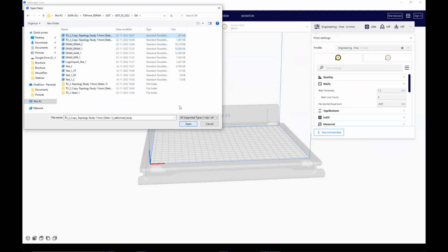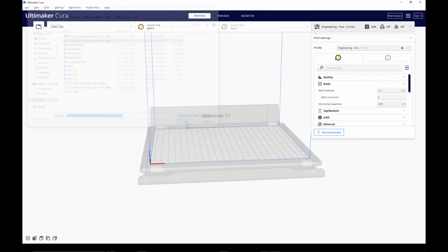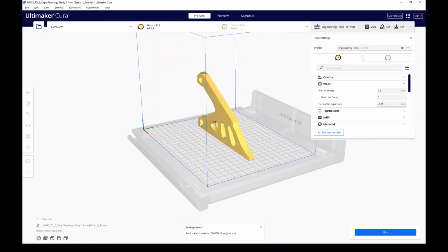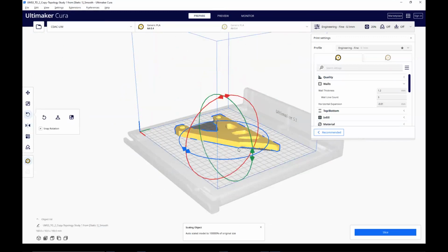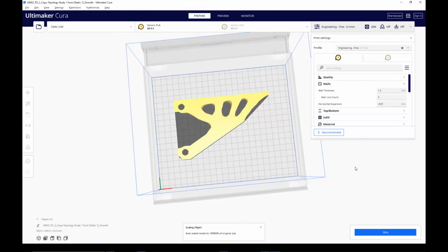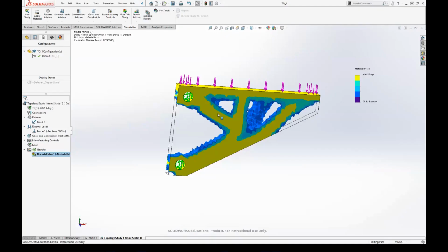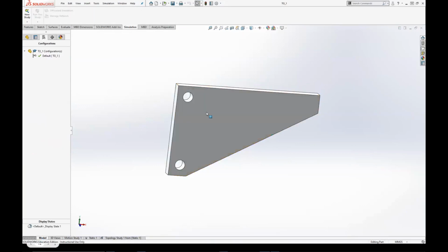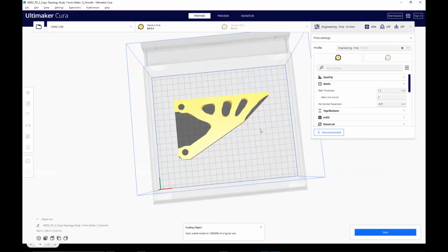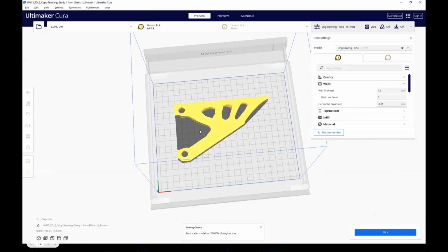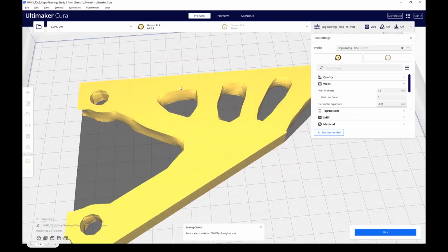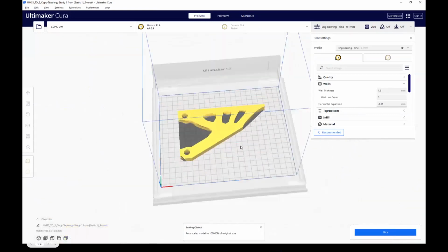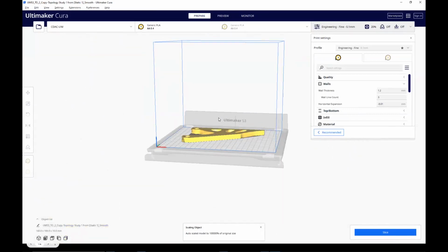So if you see, this is the smooth part which is created out of the bigger part. This was our model. Using topology optimization, we created that model into a smooth mesh like this, where we removed the excess material and were able to reduce the weight by 50%.